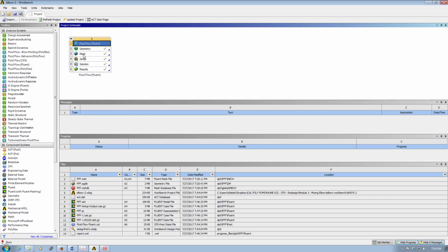By duplicating your computations, a new chain of ANSYS software modules will be created right on the right side. And I'm gonna change the name to larger inlet. Okay, now I have to modify the geometry, of course, so I click on the geometry generation.